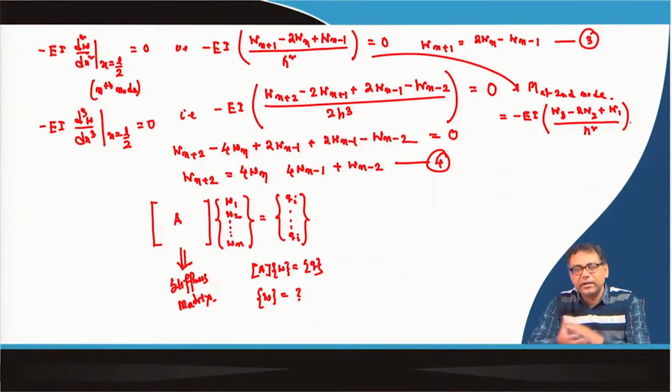Then you divide from 20 to 40, and your h will further reduce, then 40 to 80, h will further reduce, and every time you get the deformation. Then you compare the previous deformation and the current deformation. If the difference between the two deformations is very small or within the tolerance limit, then you stop there, and based on that you decide your h value.